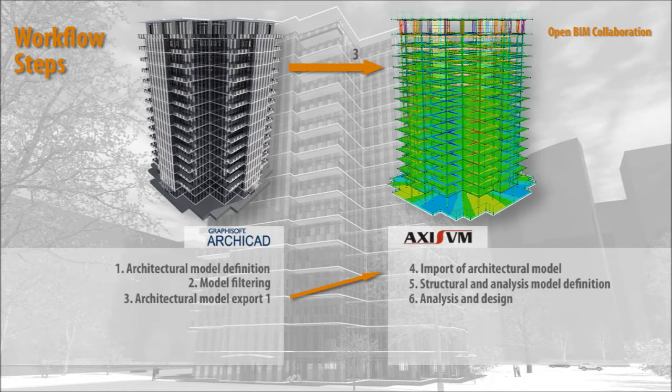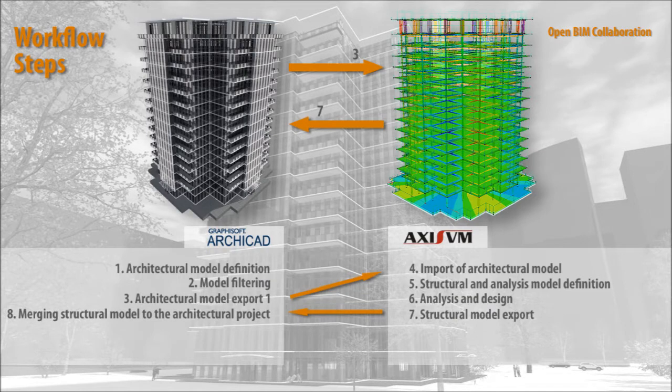They add loads to the structure and run analysis and design calculations according to the required country standard and material definitions. The proposed structural model, derived from the analysis model, can be exported back to the architects in IFC file format. The architects can either merge the structural model into their current architectural project or open it as a totally new file. Filtering is also available for the import, and imported elements can be placed on given layers.